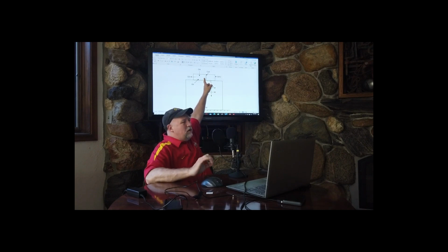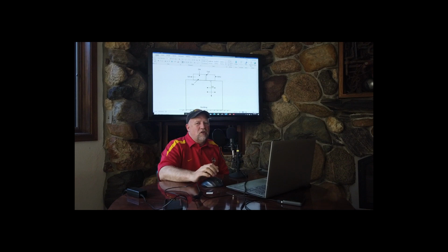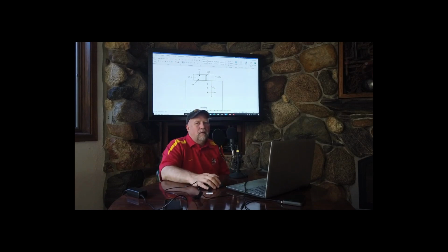That is the total difference in energy as we go from the mixed air condition, the return air mixed with outside air, across the coil and make it into supply air. The total amount of energy that we have to remove is the air conditioning load, the total coil load. The coil load is different from the space load by the amount of ventilation that we have to provide.